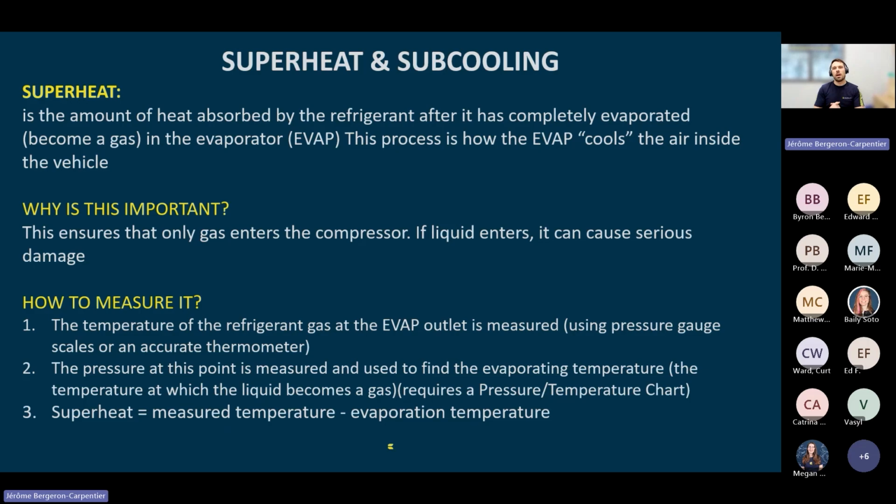Too many instructors, I should say, don't go that far with their students. They say, oh, it's too complex for them. But you really do need to understand superheat and subcooling, whatever you're teaching, traditional AC system or heat pump system. So superheat, super important.